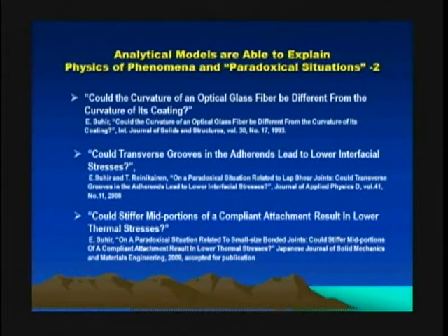Could transfer grooves in the adherence lead to lower interfacial stresses? It was absolutely unclear why they could, and it was explained based on analytical modeling. Could stiffer mid-portions of compliant attachment result in lower thermal stresses? They can, although the common wisdom is that, yeah, if you make the compliant attachment more and more compliant, the thermal induced stresses will always go down.